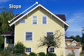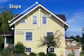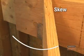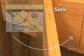Slope is the incline of a roof expressed as inches of rise over inches of run. When you change the slope of something, you change the angle in a vertical direction. To skew something is to pivot it left or right around a connection point. When you skew something, you change the angle in a horizontal direction.